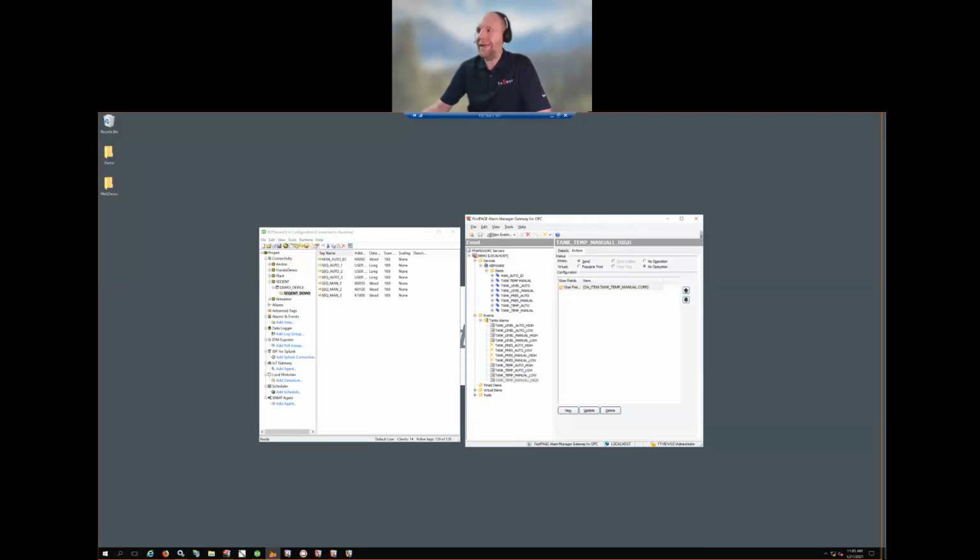I'm going to start with our gateway for OPC here. You can see that on the right-hand side. Number one, this is the application that connects to an OPC server. It acts as a client in order to subscribe to any of that data. You can see I've got some configuration here up on the screen. So the first thing that one would do in this application is build what's called a device. That's our ability to connect to the OPC server.